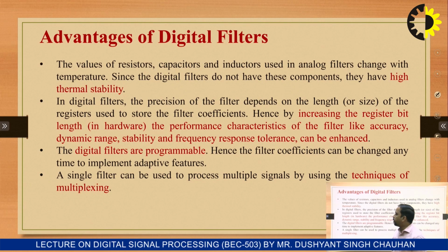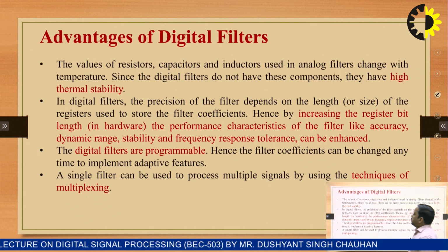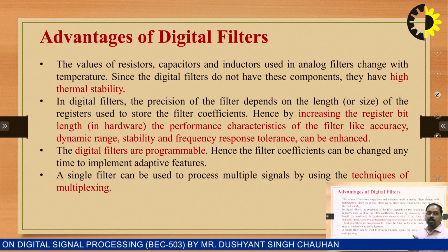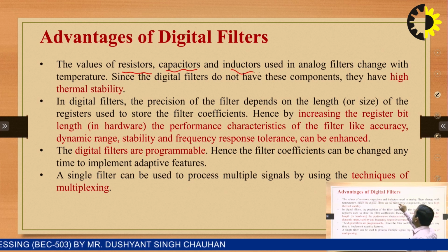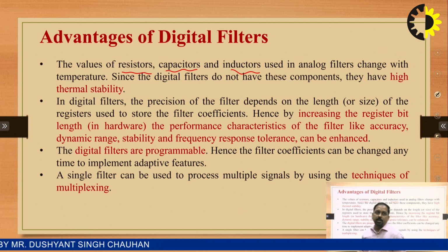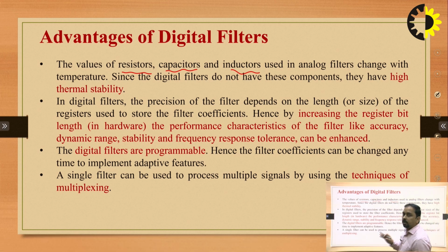Now the advantage part. What are the advantages of digital filter over analog filters? In analog filters, the values of resistors, capacitors and inductors used get changed with temperature, and digital filters do not have these components. So we can say that digital filters have high thermal stability in comparison with their analog filter counterpart.